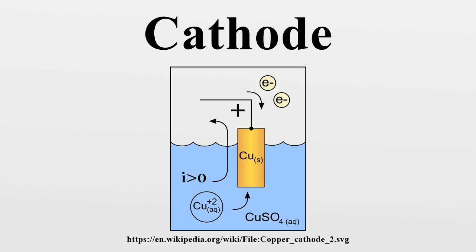Field electron emission. A strong electric field can be applied to the surface by placing an electrode with a high positive voltage near the cathode. The positively charged electrode attracts the electrons, causing some electrons to leave the cathode's surface. This process is used in cold cathodes in some electron microscopes, and in microelectronics fabrication.